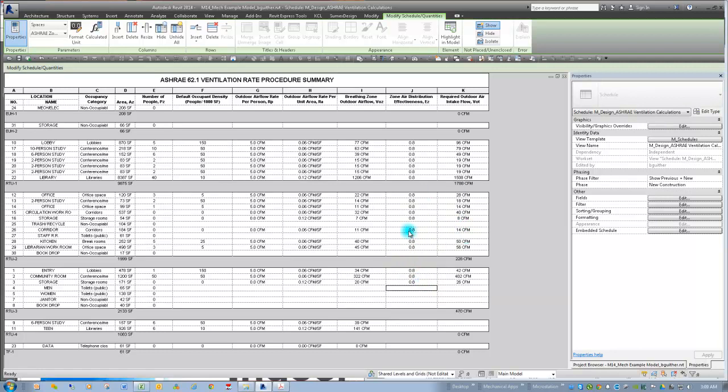The reason I'm putting in 0.8, and again, you can refer to the table in ASHRAE, basically with ceiling supply and ceiling return, it's the heating design mode that gets a 0.8 in my design in this case. Cooling design would be 1.0, but we're doing the worst case scenario. So there we go. As you can see, now we have our required outdoor air intake. And again, this is based upon single zone systems, our zones being right here, RTU1.